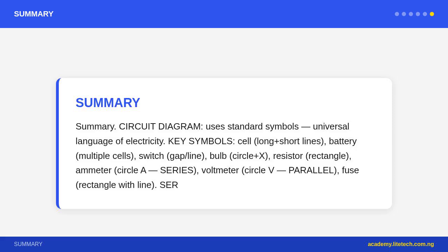Parallel circuit: multiple branches, same voltage across all, shared current, one failure does not affect others, R_total decreases, used in household wiring. Drawing rules: use ruler plus pencil, straight horizontal/vertical wires, filled dot equals junction, bridge arc equals crossing without connection, label all components. WAEC tip: practice drawing standard symbols from memory. Symbols questions appear every year.